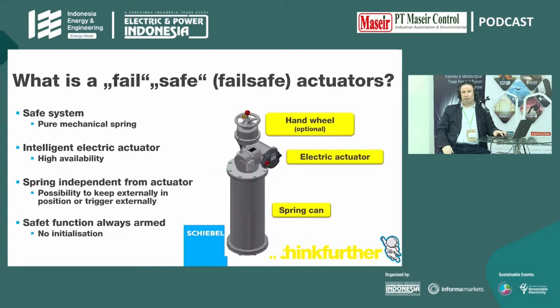What is a fail-safe actuator? What the name tells: it's basically responsible to safely close or open a valve in case of emergency. So it needs to fail to go to a safe position. So that means we are talking about a safe system.